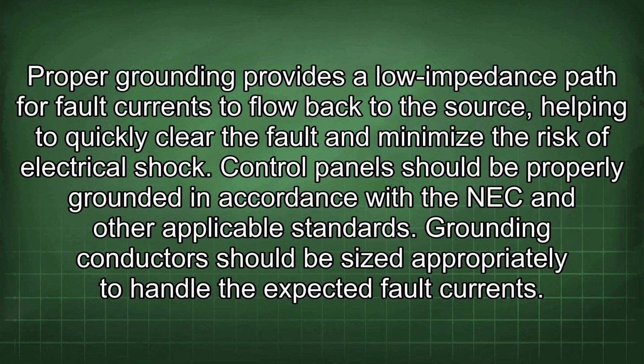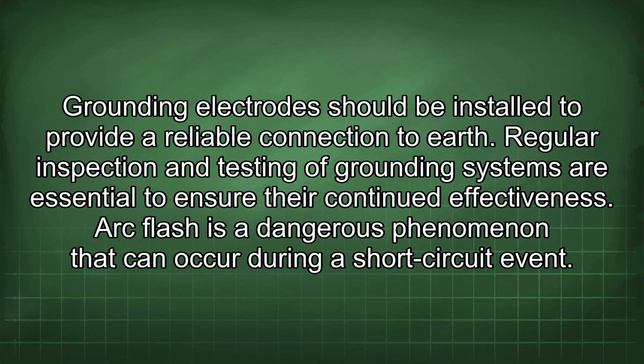Control panels should be properly grounded in accordance with the NEC and other applicable standards. Grounding conductors should be sized appropriately to handle the expected fault currents. Grounding electrodes should be installed to provide a reliable connection to earth. Regular inspection and testing of grounding systems are essential to ensure their continued effectiveness.